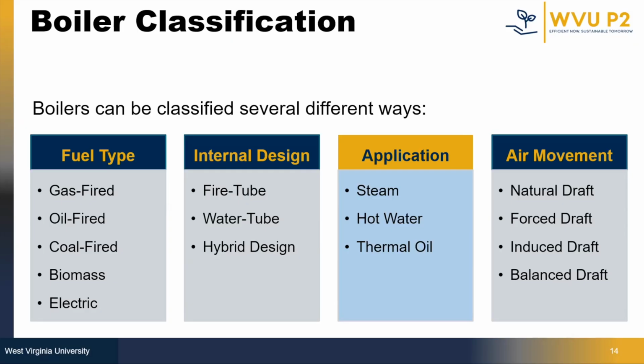Then there are thermal oil boilers, which heat specific oil that carries heat through the facility. Unlike steam, thermal oil works at low pressure, can reach higher temperatures, and doesn't freeze. And it is not corrosive. That makes it a good choice in some cases, though steam can be more efficient where latent heat is an advantage.